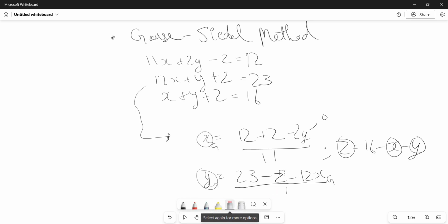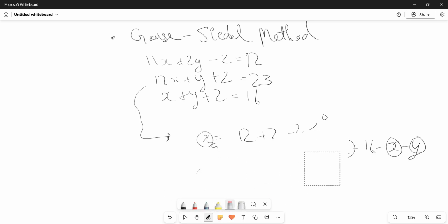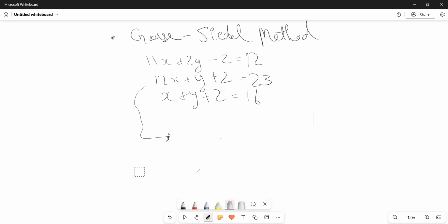Then you keep doing all these, you keep iterating it until your values converge, right? So the criteria that you choose your model or solver or method is based on how fast you can achieve convergence, or how fast your residuals can be decreased, right?